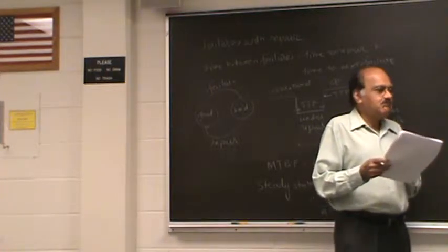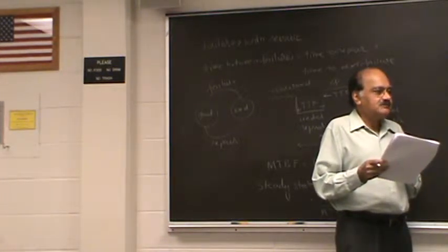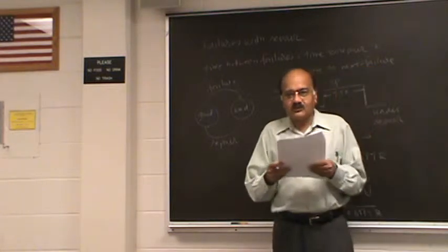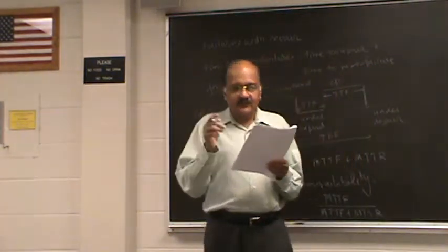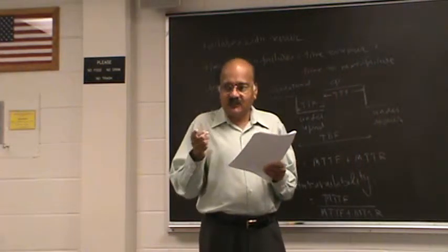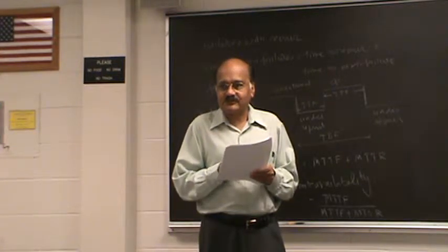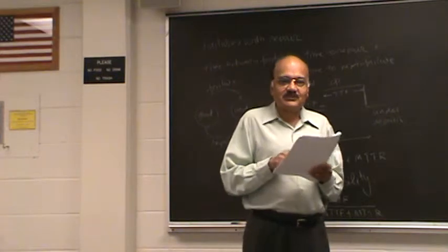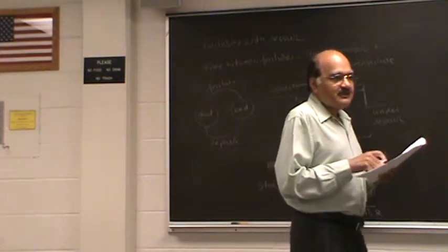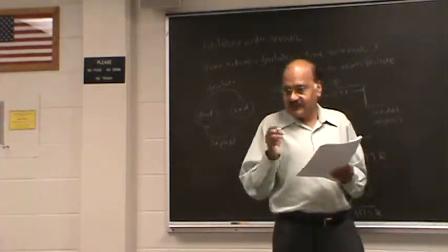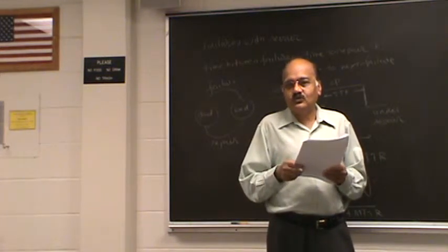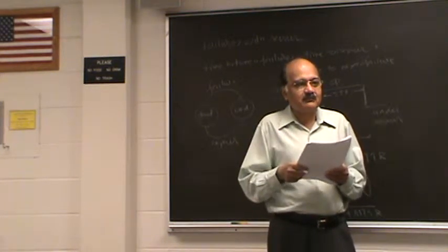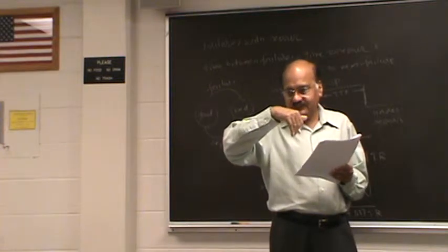Well, I guess maybe I should add something more. Sometimes if you are designing asynchronous circuits, have you been involved in designing asynchronous circuits? Yeah, I did. Okay, so in asynchronous circuits, sometimes the redundancy is intentional. So sometimes if you don't include a redundant term, then there's a possibility of a glitch.